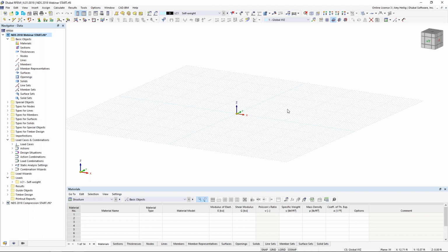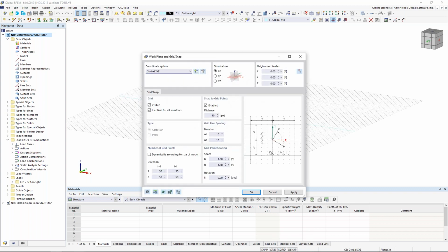So once we are done defining the base data, we will be brought into the main program, and we can see our drawing grid activated here. Well, we can modify those drawing grid settings by right-clicking at grid down at the bottom. My default spacing here is set at 1 foot. If we see anything other than this, for example, when you first start the model, you might see something like around 3 feet. You can always hit this default option here to go back to the 1 foot or adjust this to maybe 0.5 feet. We can also open up our units here and change this to inches if we're working on a much smaller scale.